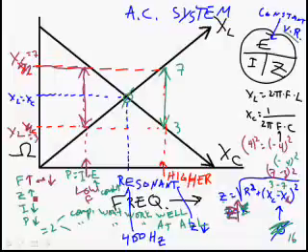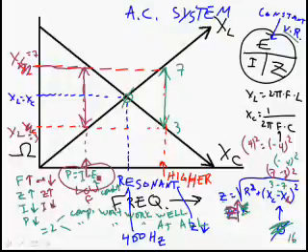If Z goes up and we have a constant voltage, opposition of current flow goes up, current flow is reduced. So current flow also goes down. If current flow goes down, we've got P equals I times E. E is held constant by the voltage regulator. I is going down, so now P is going to go down, or watts are going to go down. Wow, if watts go down, our components won't work well, or our components won't work at all.